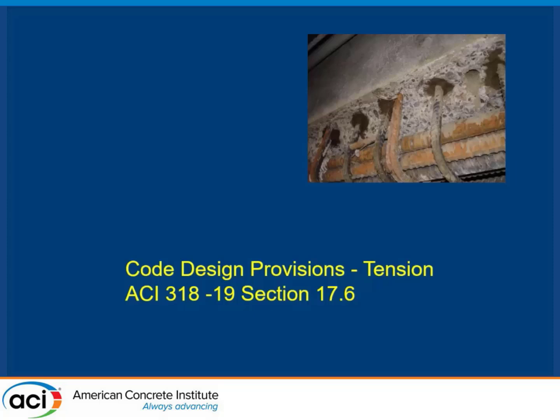When you have the undercut anchors, which for many structural engineers is their go-to, well, that takes a whole extra step, and that's one that really kills it for the contractor. In fact, I have to drill and then drill again and then install. That's what happened in the Big Dig. Like I said, we got ahead of things. So okay, one more question and then it's all right.